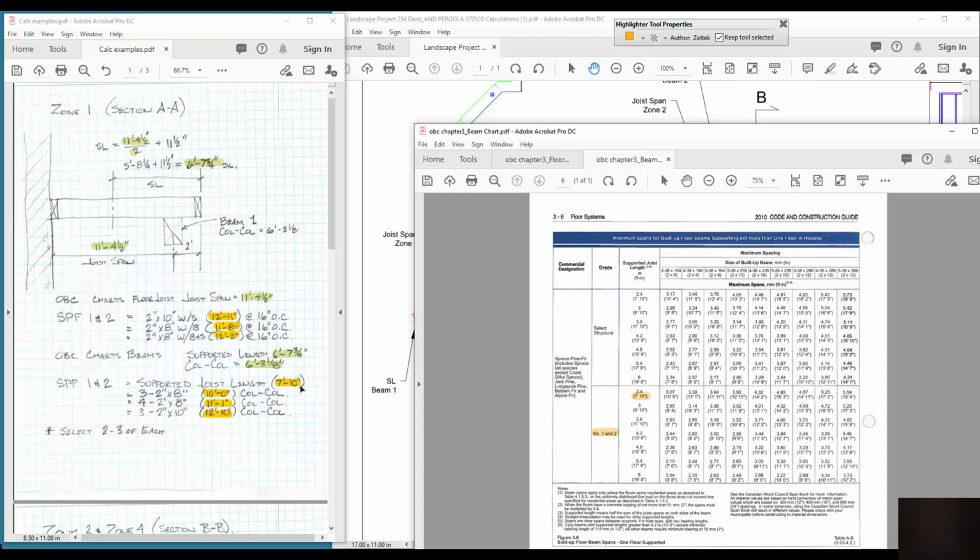Now I'm looking for the beams. So my first one with a column spacing of 6 foot 3/8 is the very first one that's on here. It's a very tight or close spacing, so I've indicated that one. And I want to do groups of 3. So I'm going to try to find a couple of 2 by 8s. So this one's slightly bigger, not that I need to know that. And then the next group of 2 by 10s, I've got the one at 12 foot 10s.